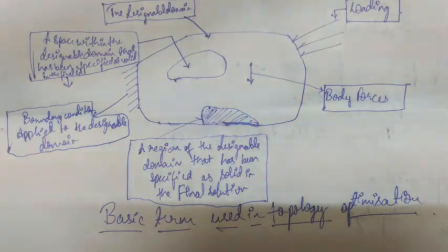Shape and size optimization are more limited than topological optimization, in that the designer must specify the topology of the proposed structure, which is then fixed through the optimization process. The general form of the topological optimization problem is to derive the optimum distribution of material within a designable domain to fulfill a given objective.